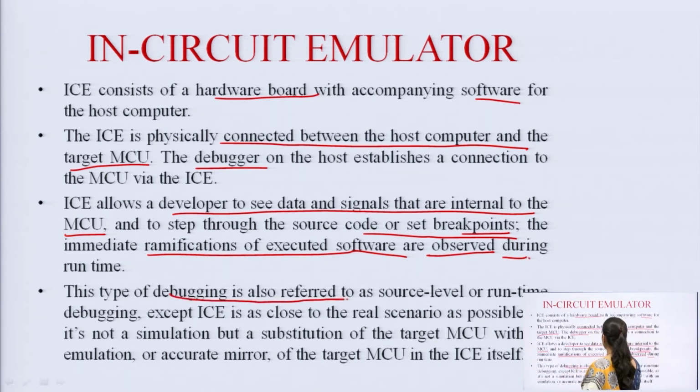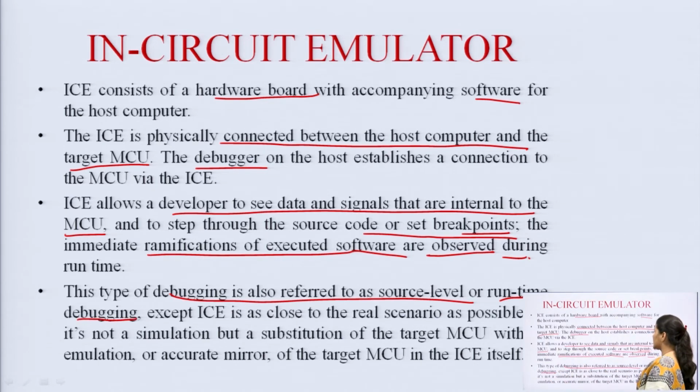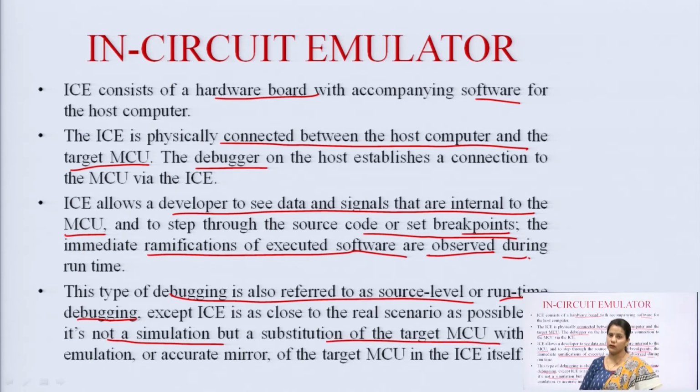This type of debugging is also referred to as source-level or runtime debugging, except the ICE is as close to the real scenario as possible. It is not the real scenario, but it is as close as possible to it, which is why it is not a simulation but a substitution of the target MCU with an emulation or accurate mirror. Emulation means a mirror image, that is, not the product actually but a copy of the product. In this way the ICE works.